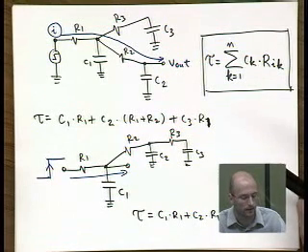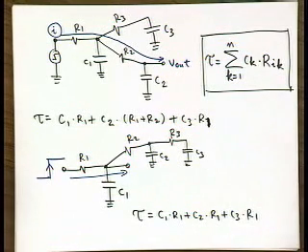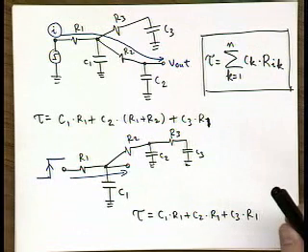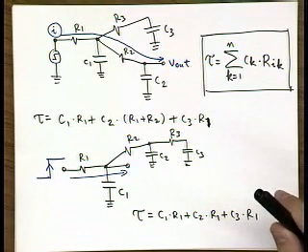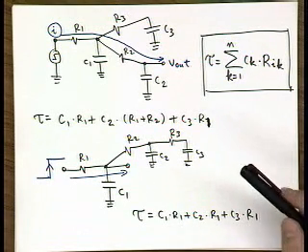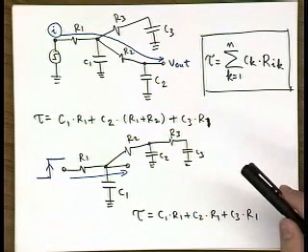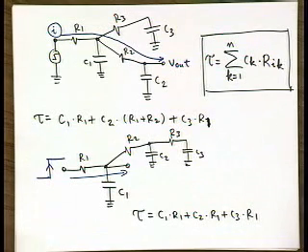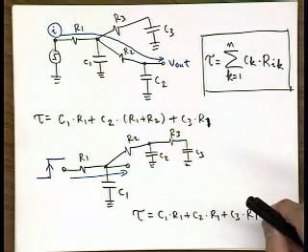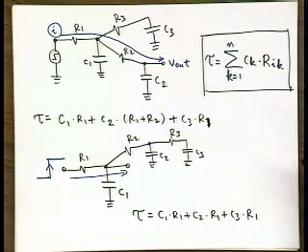If you have too large a discrepancy, then this model becomes a little bit inaccurate. But luckily, the way you model your RC networks is by extraction of certain parameters for a given length that is approximately equal in all segments, so you end up with approximately the same values, or at least within an order of magnitude.